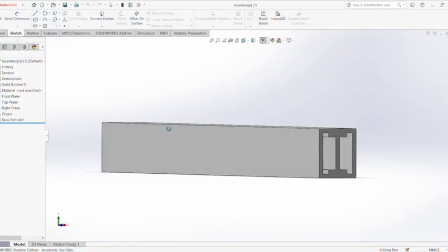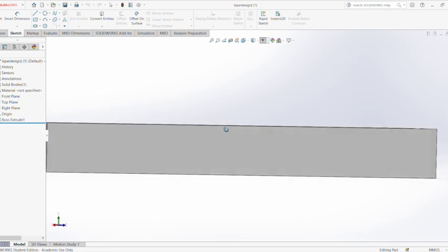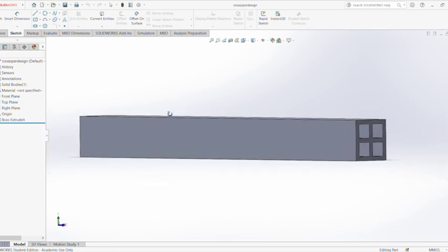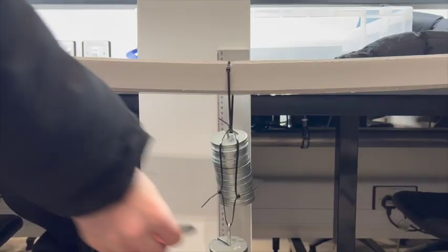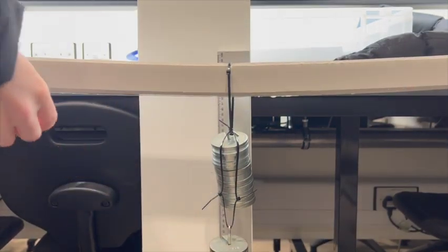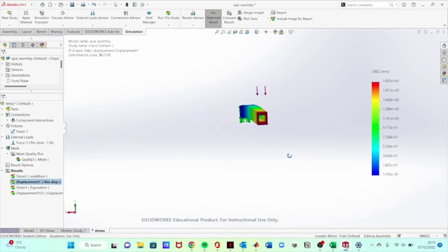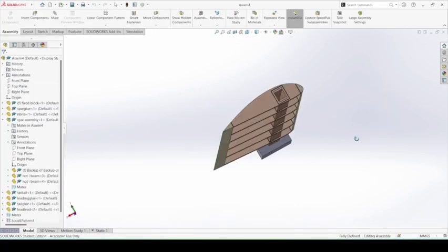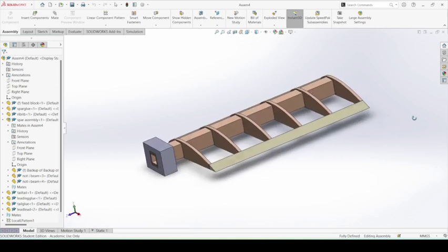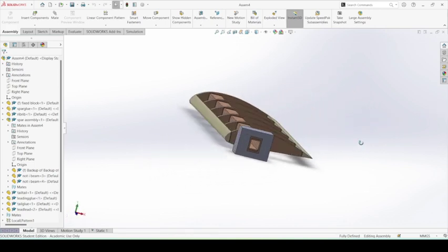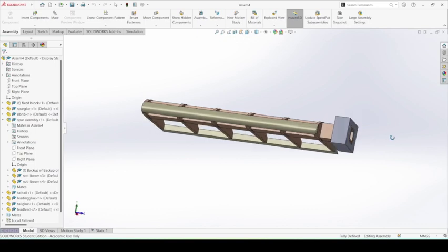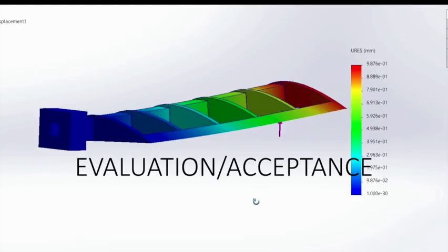We tried several different spar designs, but found that using a hollow rectangular beam with additional foam board stuck on 2 opposite sides was the most effective. The cross-shaped beam was found to be too strong as the spar didn't bend or break under stress. We then tried an I-shape, however the beam was still too strong. Ultimately, the reinforced hollow rectangular beam was the one to fit the specification and be used in our final design. We considered how we could reduce the overall weight, for example by cutting holes in the ribs, but decided that the little weight we'd save wasn't worth the time and resources it would take to complete.